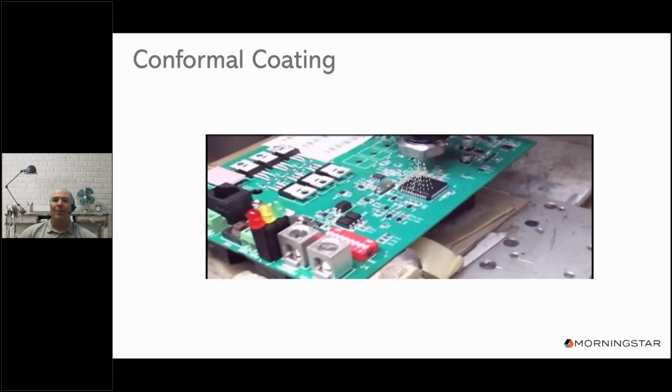Conformal coating is applied by a spray that goes over the circuit boards to protect against dampness and corrosion. The nozzle that you see in this slide sprays a very fine mist of epoxy or silicone coating, and it travels up and down and across the entire circuit board to apply a coating that will provide additional protection against moisture, dust, and other contaminants. We use surface mount components that are precisely assembled by machine, not hand assembly, so this makes for a very reliable, high quality product.